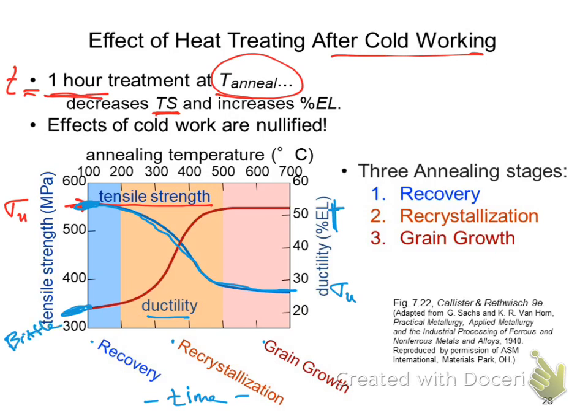And then over this process, we have regained our ductility, but we've lost some of our tensile strength. And it just depends on what we want. If we wanted that high tensile strength and we were okay with it being brittle, then maybe that's what we wanted. But if the process of manufacturing to be able to produce the end result object or the widget that you want in the shape that you want it,